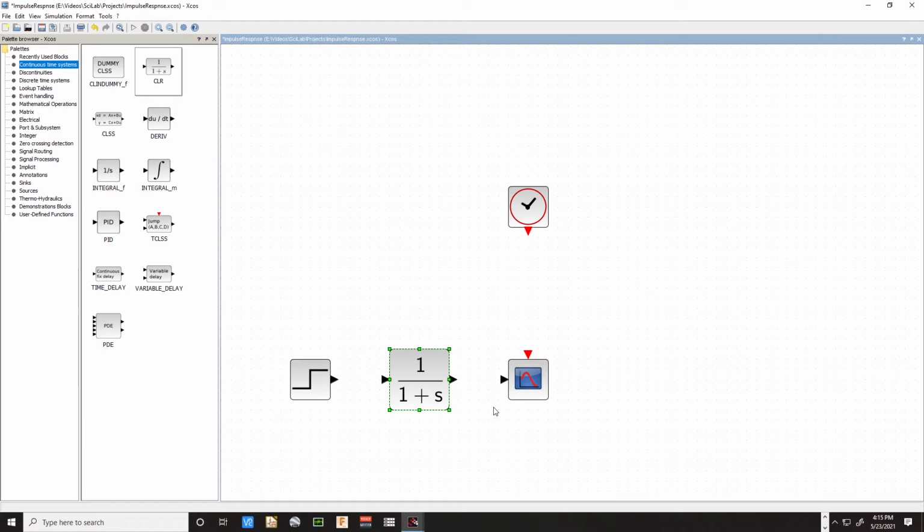If you read the documentation, it will tell you that this is a polynomial that goes in here, and you can put a polynomial in, and I'll show you in a minute how we can set the polynomial to what we want. It's in a very special form, and they'll tell you it must be in S. Well, if you're not familiar with Laplace transforms, that's what that means.